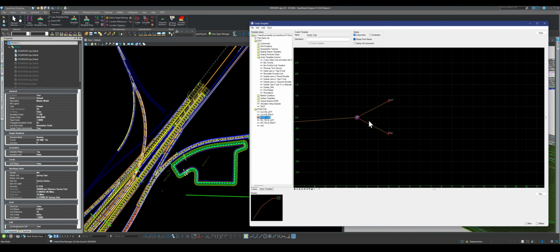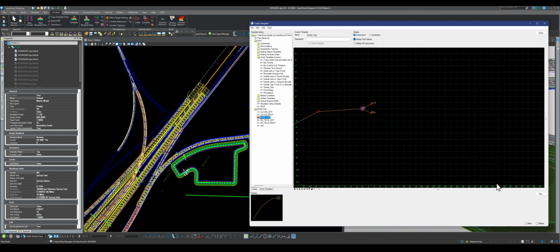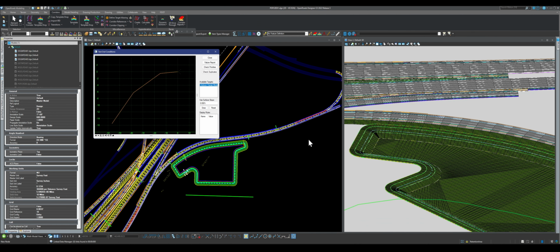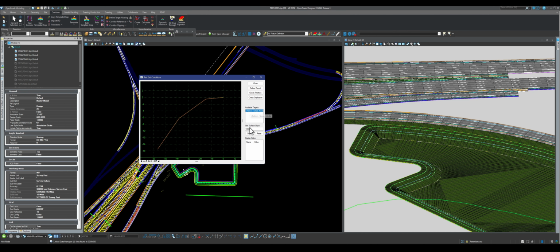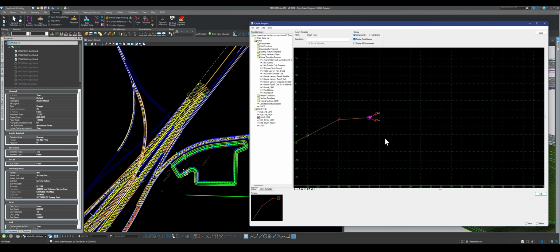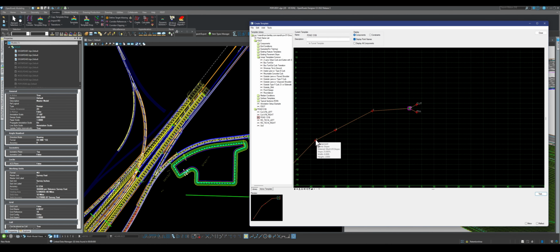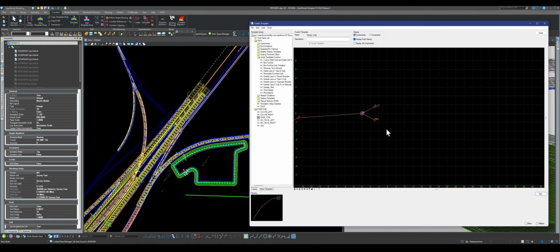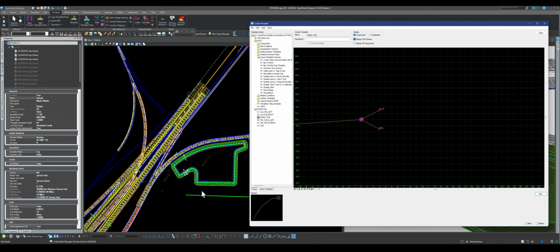Okay, but before we leave here, now we have it, it's perfect. And let me show you test. So if we go to test here, okay, and then we have this active and you click on draw. So imagine with me, this is the surface, the white thing. So if I go up and down like this, that's the condition of cut and fill. So let's close this. And by the way, don't worry about the message when I clicked on test. It popped up again because I did not name these or give them the proper features. It's already warning you. But as you know, we don't need these everywhere. I only need them here. I don't need them here. Here I just want the roadway to take care of that, right?